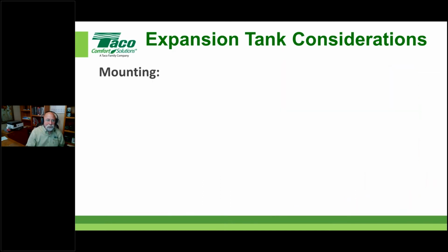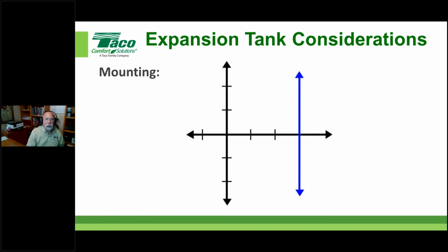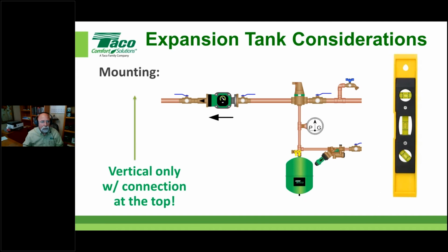All right. Very good. So, mounting. Well, just think of verticals, folks. There was a time, and I even had a copy from one of the major expansion tank manufacturers in the residential world, showing you could basically put it in any direction you wanted to. But there was some empirical data coming back that said we need to change this up, and they actually changed their installation booklet to just say, look, mount it vertical, okay? Connection at the top, kind of like we're showing in most of our drawings. Sometimes there's just not room on the drawing and it's shown wrong.